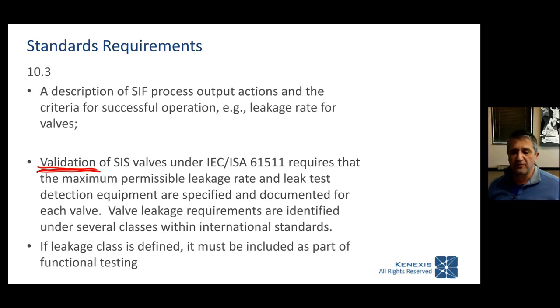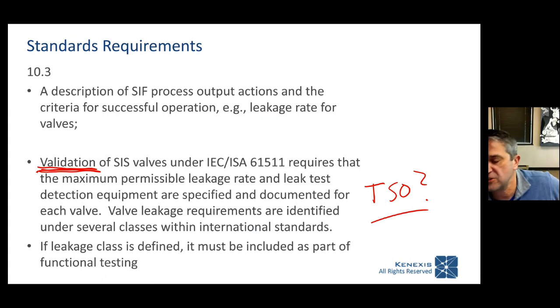Now, you could do this in a number of different ways. If you have isolation valves and upstream and downstream bleed valves, you could do a leak tightness test in situ with the valve where it is, but you might need to take it back to the maintenance shop to perform a bench test to make sure that the valve leakage requirements are achieved. And if it says TSO, how much is it allowed to leak? More on that coming up. The answer is, I don't know, not really defined anywhere, but I'll come back to that.